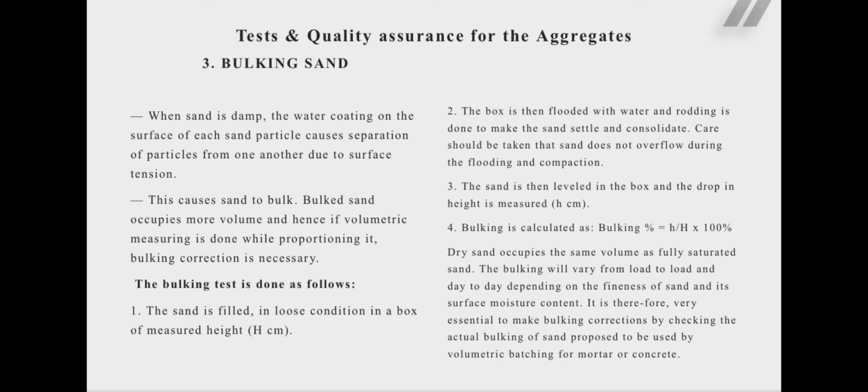Dry sand occupies the same volume as fully saturated sand. The bulking will vary from load to load and day to day depending on the fineness of the sand and its surface moisture content. It is therefore very essential to make a bulking correction by checking the actual bulking of the sand proposed to be used by volumetric batching for mortar and concrete.